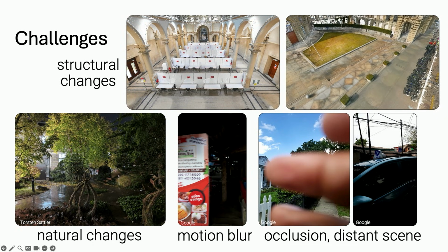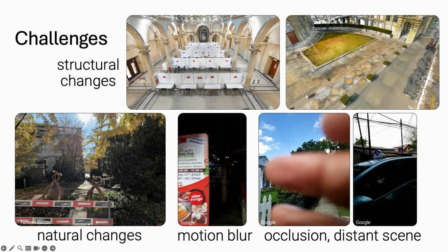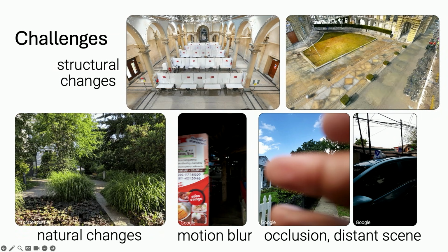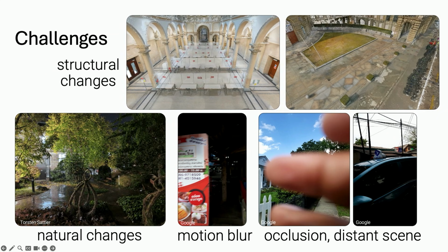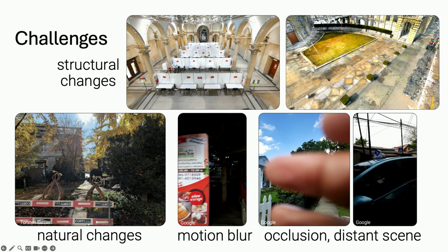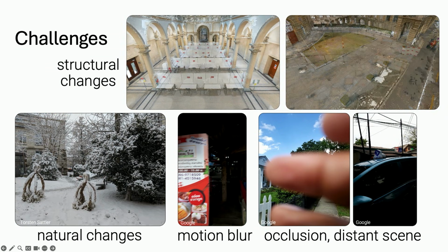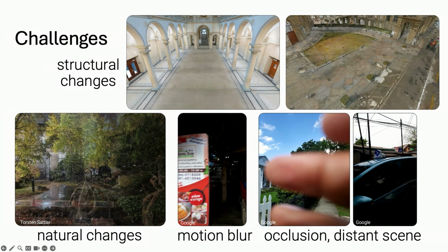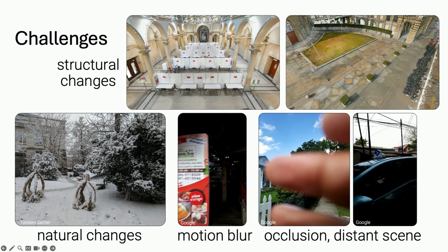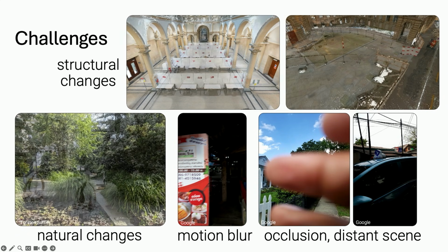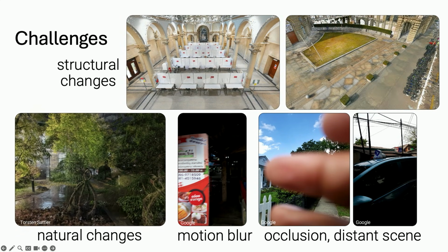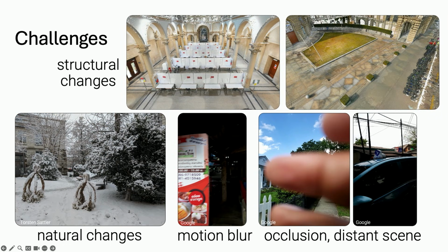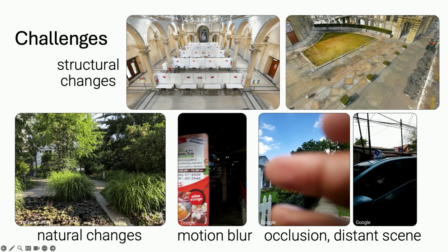If we talk about single image visual localization, in nominal cases it's pretty much solved, with quite high accuracy and robustness with respect to a 3D model. People generally do image matching, propagate the 2D image matches to 2D-3D correspondences, and do PnP plus RANSAC, and you can get a very accurate 6DoF pose if your calibration is accurate.